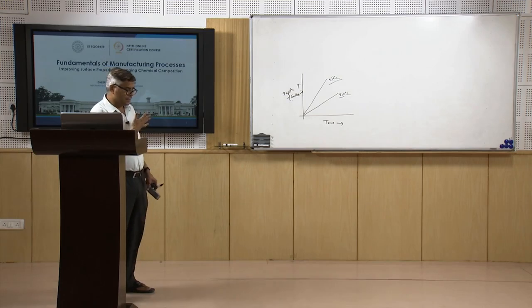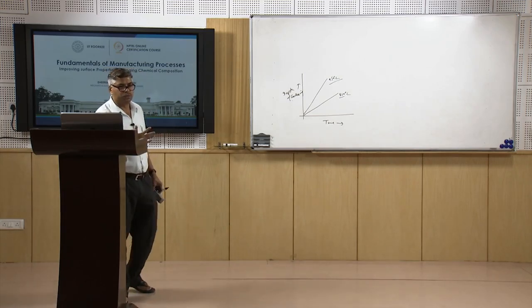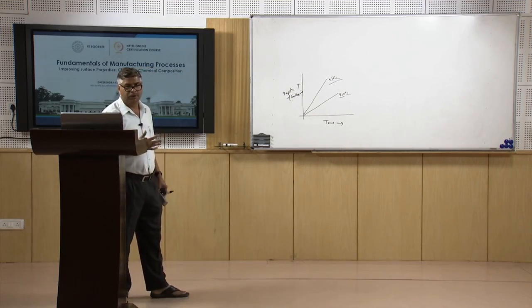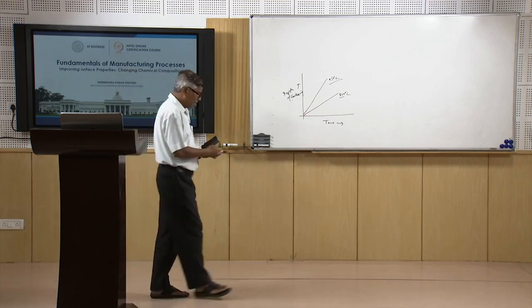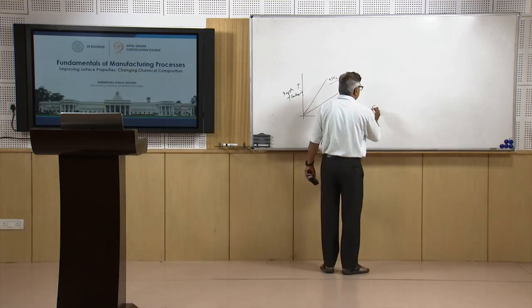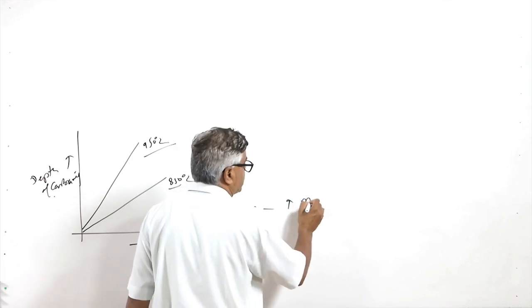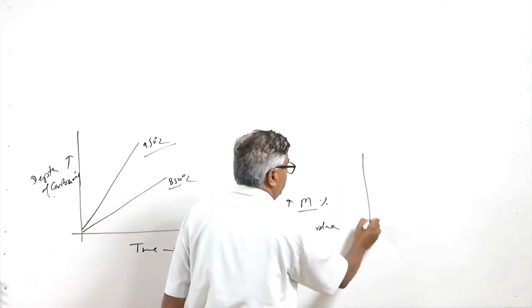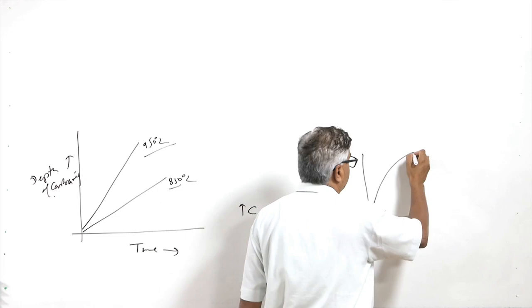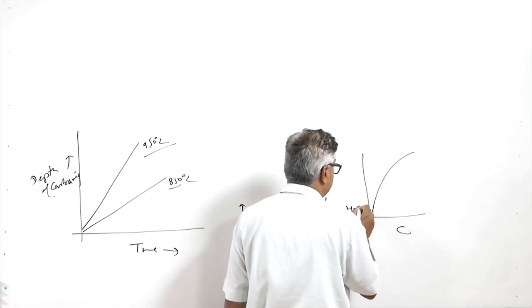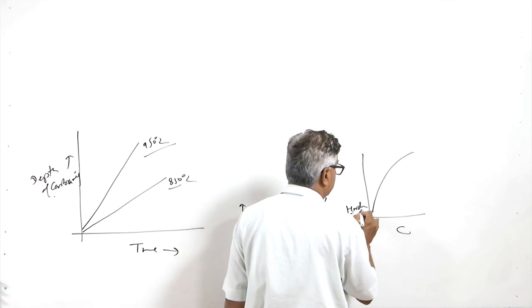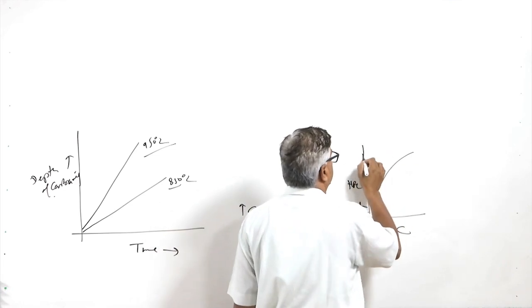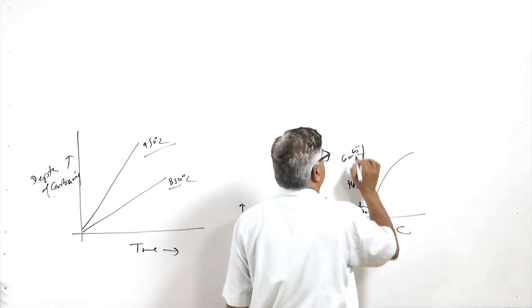And we know that carbon directly affects the kind of phases which will be formed, the amount of martensite which will be formed, and the hardness of the martensite. So an increase in carbon content increases both the martensite fraction and the hardness of the martensite. We know from this diagram that martensite may be found, but the hardness is less, maybe like 30 or 40 HRC,